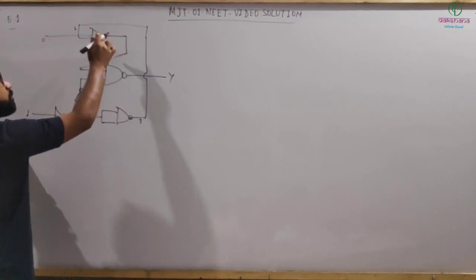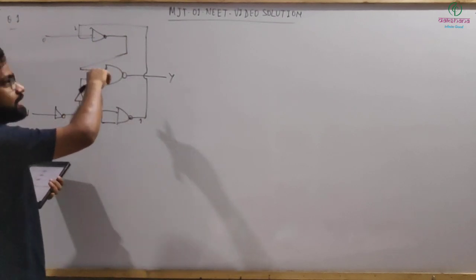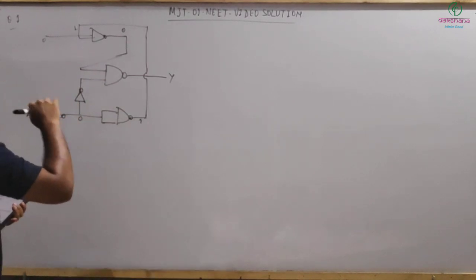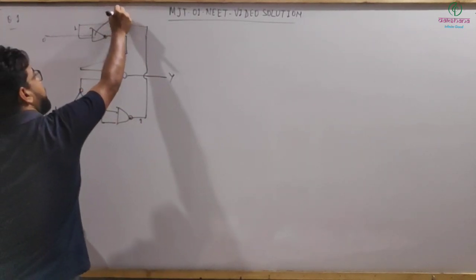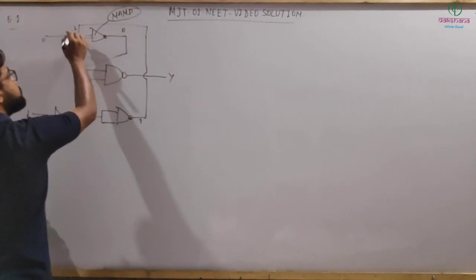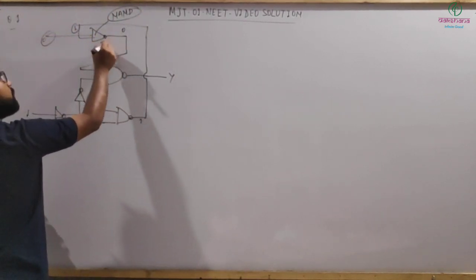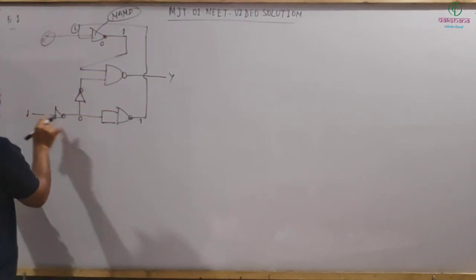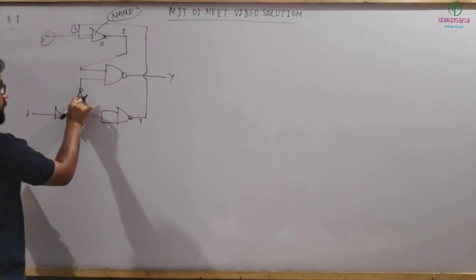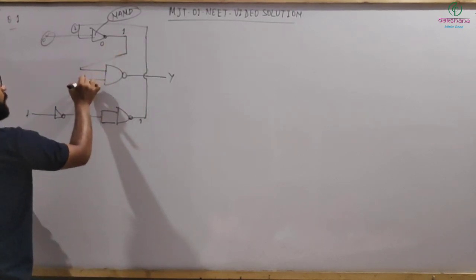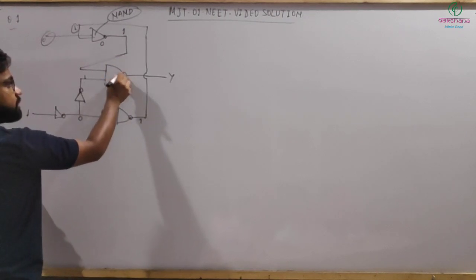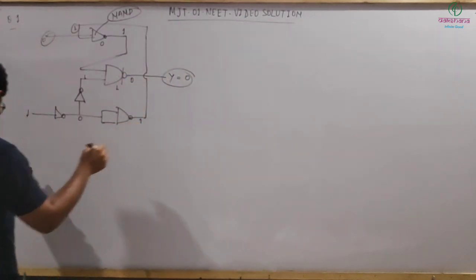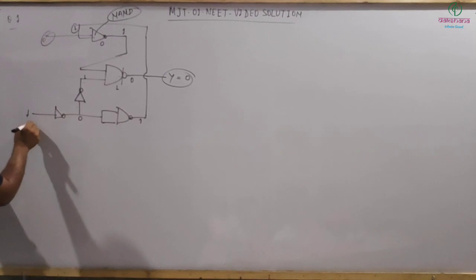its output, because it's a NAND gate, is 1, inverse of that will be 0 here. So it's 0 comma 1, then the output will be 0, and then the inverse of that will be 1 here. And here 1, so NOT gate 0, again NOT gate, it's 1, so 1 and 1. So we will get 1 here, inverse of that we will get 0, so output y is coming out to be 0, which is matching with option number 1. So the correct answer is 1.